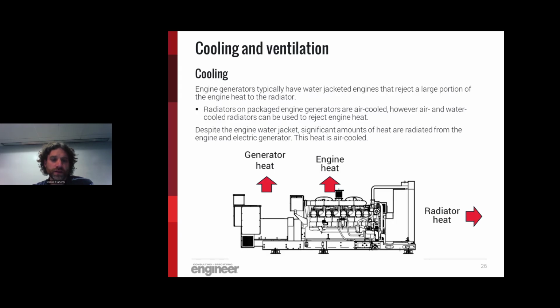Now we'll look at some cooling and ventilation issues. Engine generators typically have water-jacketed engines that reject a large portion of the engine heat to the radiator. The radiators on the package engine generators are air-cooled. However, air and water-cooled radiators can be used to reject engine heat. However, if these types of radiators are used, they're typically remote-mounted.